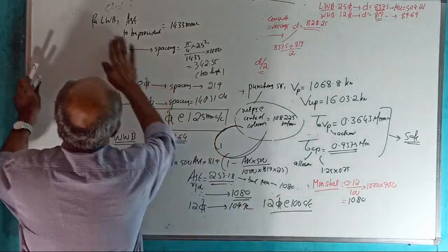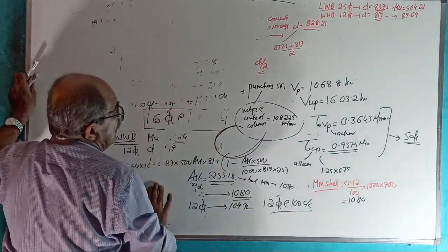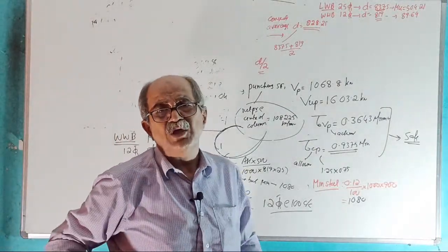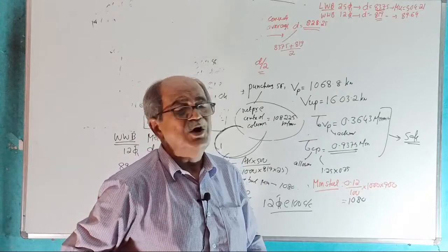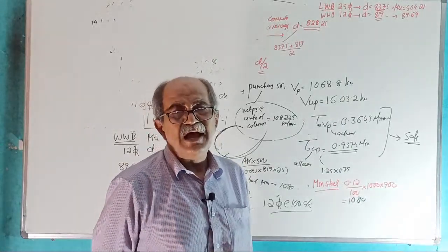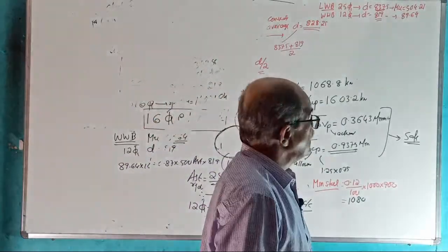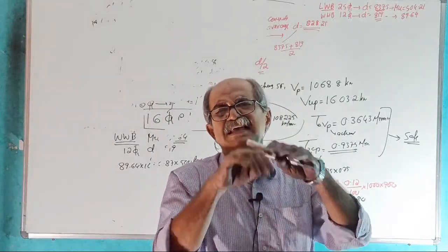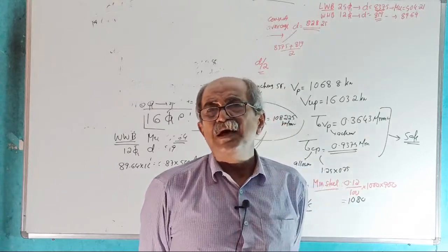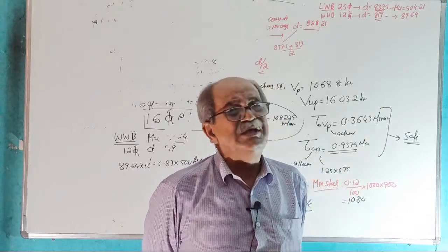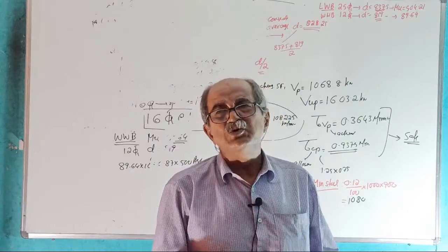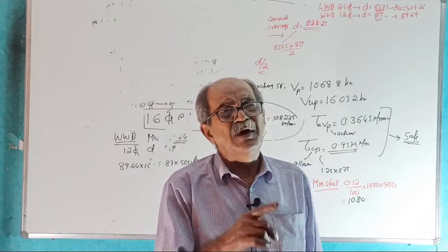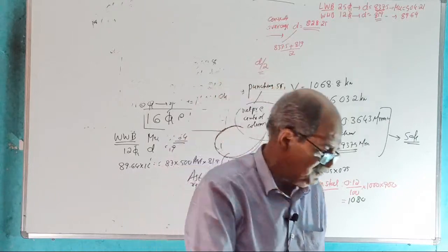Remember. Therefore, now I will do one thing. Check for shear. You can do it now. I don't want to waste the time, because this is an extra question I solved for all these problems. Check for shear. Can you do it? Critical section at D. Lengthwise bending you check. Widthwise bending check is not required. If the lengthwise bending check passes, widthwise will be laughing at it. It will have such a small shear force. Lengthwise bending safe means widthwise bending 100% safe.